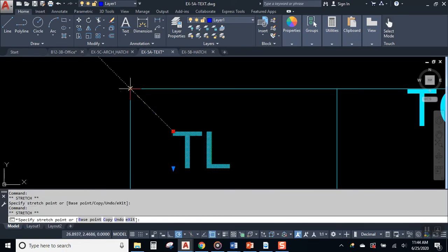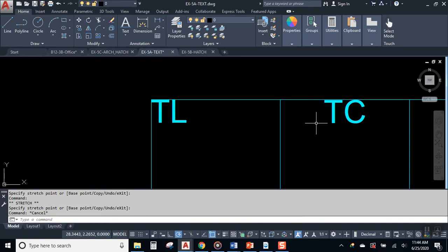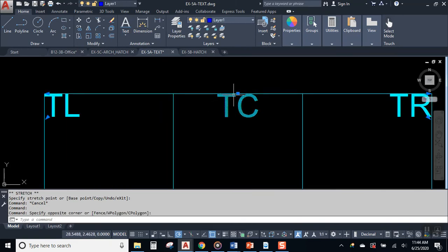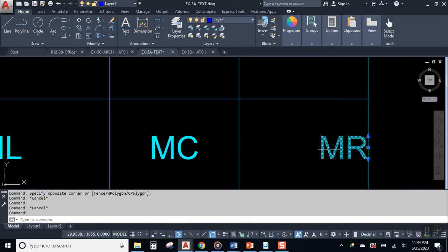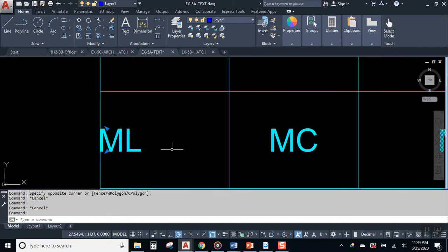So you can stick it exactly, precisely where you want it. Top center has a grip at the center of the text string and at the very top edge. Top right has it in the top right. Middle right on the right edge, but in the middle, top to bottom. Middle left is the opposite, in the left edge, but in the middle, top to bottom. Middle center is kind of like just regular middle.